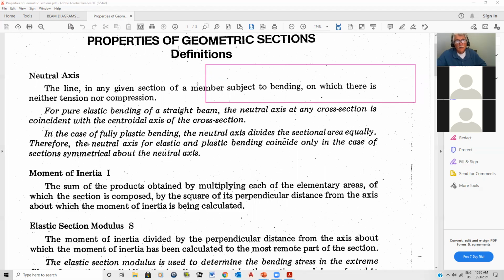Okay, line. And if I can find the neutral axis here, that means at this point all the stresses are 0. So if I have a beam that is being supported here and here, and I need to make a hole in my beam where I know it's going to affect the beam as little as possible, if I make my hole here, it's going to have very little consequence on the strength of my beam because the stresses here are almost 0.